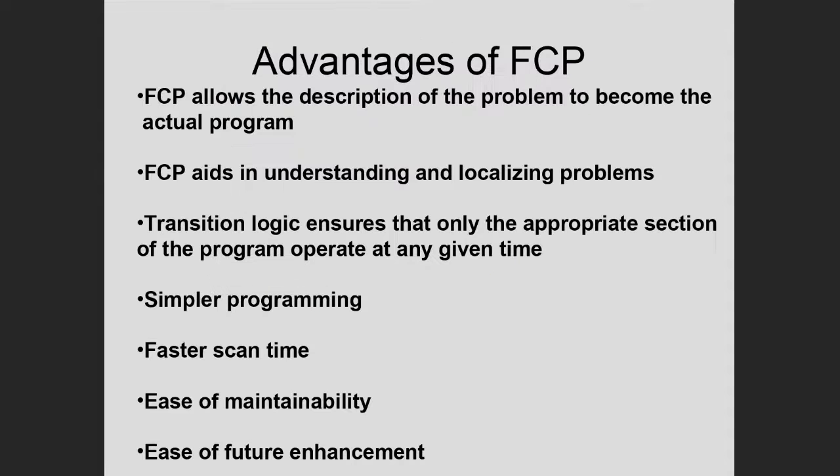And so programming this way has several advantages, some of which I mentioned already. I like this first one that says with function chart programming, the description of the problem becomes the actual program. In other words, when they hand you the description of the problem and you flow chart it, like I showed you in the second slide today, each one of those parts of the flow chart becomes a little mini program. So just by understanding the problem and describing the steps, you're basically defining the program.